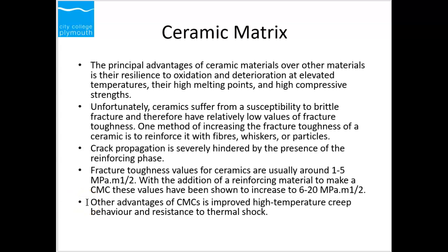The main advantage of ceramics is that they are resilient to oxidation and deterioration at high temperature. They can withstand high temperature. They have a high melting point and high compressive strength. An example is concrete. Now, the issue with ceramics is that whenever they fracture, they go through a brittle failure. They do not have a high value of fracture toughness.